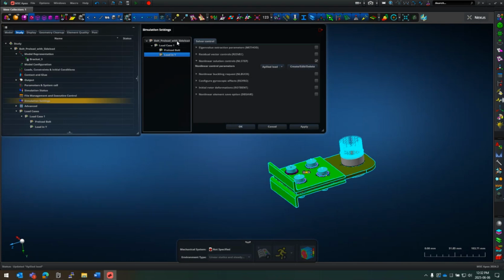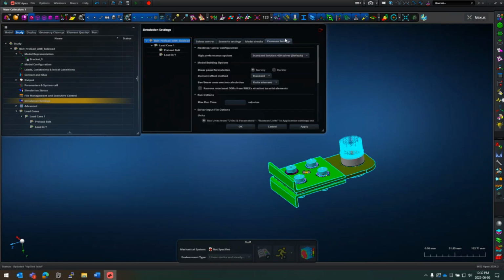And just one interesting one. This was added relatively recently, so there's improved settings in terms of runtime. So there's a couple of changes it makes in terms of how it solves. It tends to use less iterations, and iteration goes faster. Which one you pick doesn't matter in terms of accuracy or results. This one just runs faster. Now, for this model, the difference was 2 minutes versus 1 minute for the runtime.